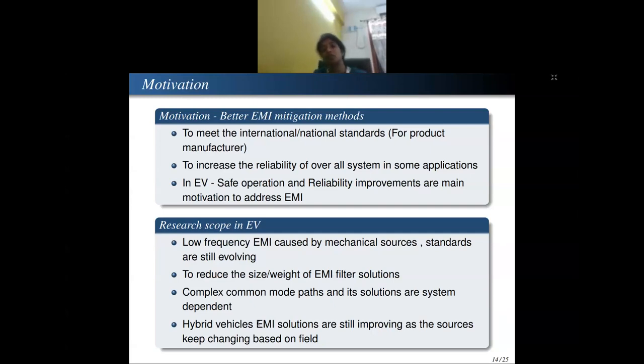And if you are going to make some overall system, see what I will do: I'll buy a converter, and then I'll buy a motor, and then I'll check what source I have. I'll try to formulate a system for a particular application. Say in my house, a product manufacturer will come and install it, correct? So unknowingly, if we place a long cable, automatically the EMI, whatever met the standard, will not be applicable in the overall system. It will create a different EMI in your system.